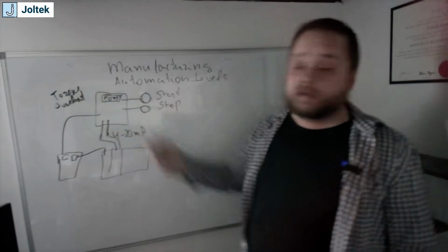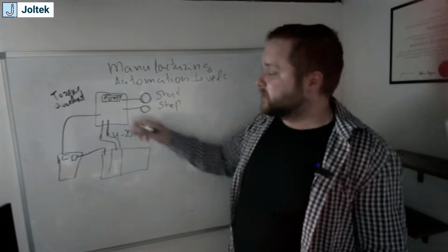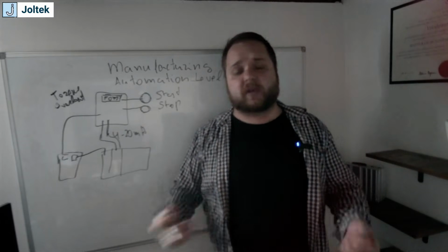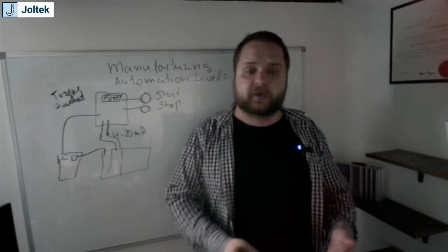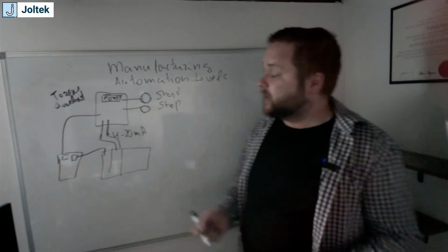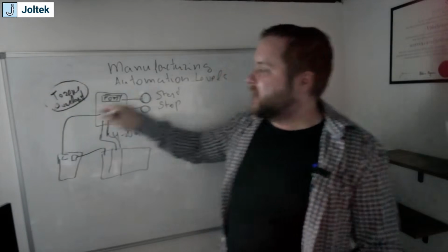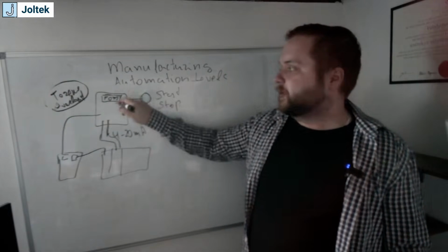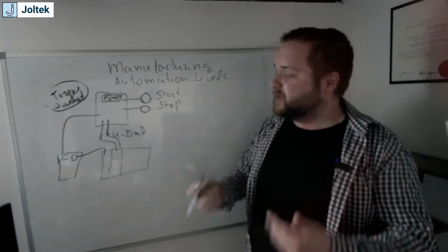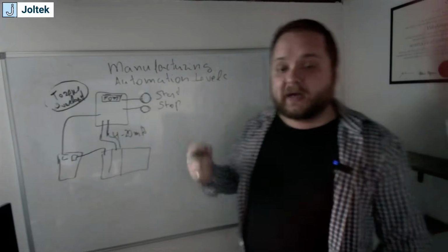And this immediately tells me as an electrical engineer that there's an overload, obviously, with the process, but I can go see where this VFD is connected. And a lot of times it's going to be some kind of a process jam. Maybe the materials were incorrect. Maybe the raw ingredients were not to spec. But ultimately, I can see this warning without having to open the panel and look at fault 73, then having to look in the manual and then realizing that it's torque overload. I can write that to the operator directly on the HMI screen.